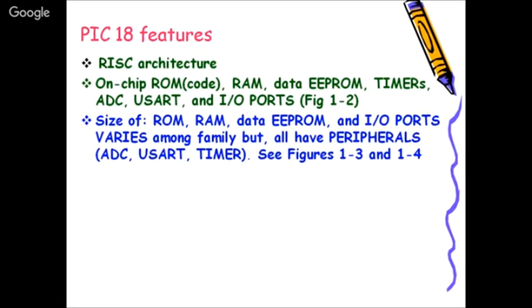And RAM also, once again, in case of 8051, how much RAM do we have? 128 bytes, 256 bytes. So maximum, Intel's 8051 has 128 bytes, and Atmel's gives 256. And mostly these 128 bytes are consumed by your special function registers, which are mainly used for controlling your on-chip peripherals like timer, counter, serial ports, etc. Whereas in case of PIC, you will see that it has got 4 kilobytes of RAM, and out of them, obviously, 256 bytes are reserved for your special function registers.